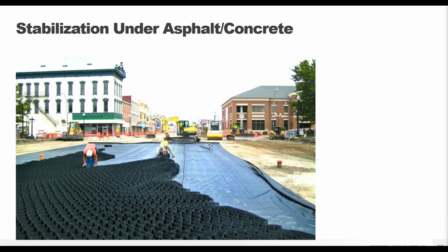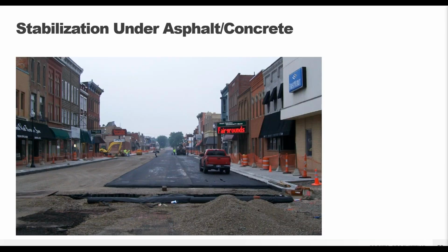And you can still get that thinner cross section of your base layer, usually 50% is what we like to aim for, which means that there's going to be less excavation required on site. That's going to be great if you do have shallow public utilities. This was a replacement of a roadway through a small downtown. And so they obviously didn't want to have deep excavation because they already had things like water pipes, utilities, all sorts of things underground that they didn't want to have to mess with.